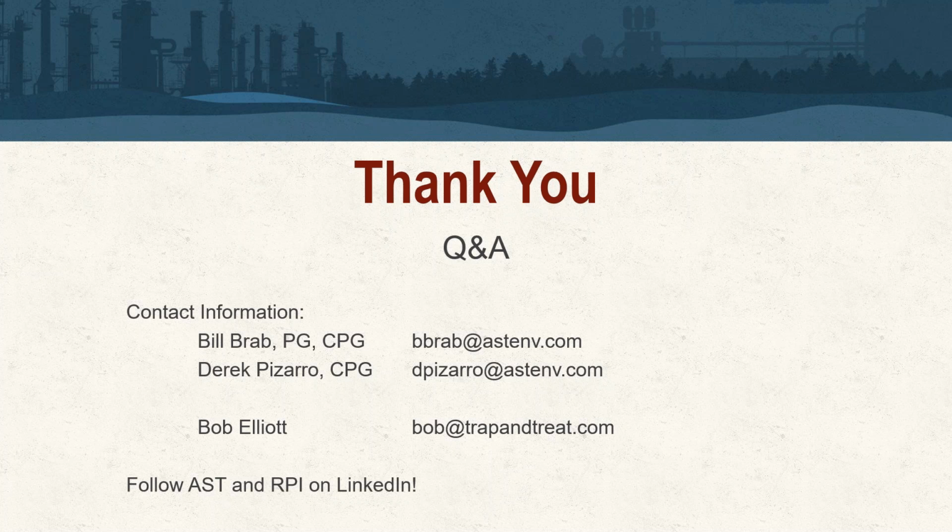To get a little more specific about the freshwater question in the instance of remediation, the typical freshwater test we utilize uses a smaller triplex unit. It's a small Caterpillar pump capable of an upper limit of 25 gallons per minute, with an upper PSI rating around 2,000 PSI, if I'm not mistaken. We can do a standard freshwater test with the triplex itself, but we typically reserve the triplex strictly for slurry injection. But as we showed in the extended graph with formational resistance, the freshwater test was actually initiated and sustained with the larger triplex unit itself.